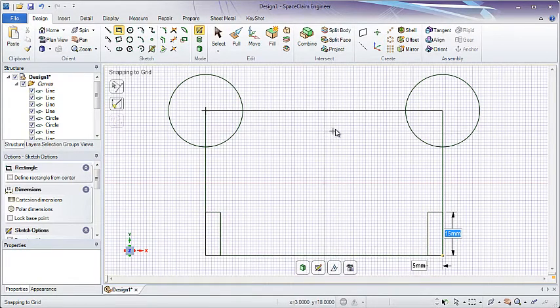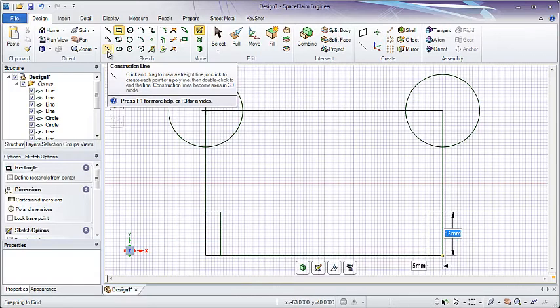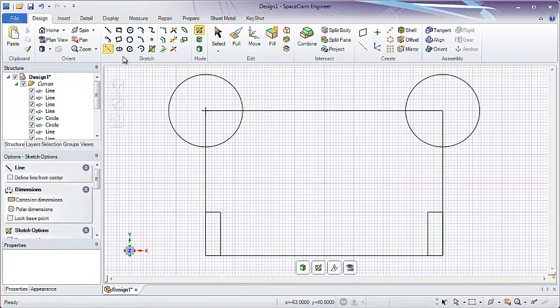Now, you might have noticed that everything we've been creating so far has been symmetric. A lot of times people will sketch only one side of your sketch and have it mirrored to the other side. To do this, I commonly create a construction line. What I'll do is make a construction line bisecting the model. Notice the green triangle near my cursor. By clicking on that green triangle, it'll let us snap to the center of the line.